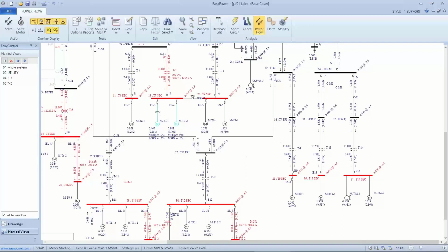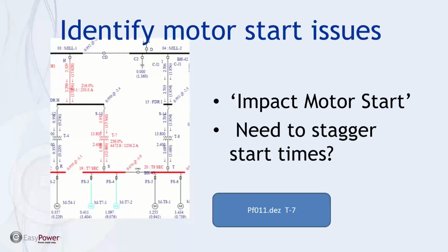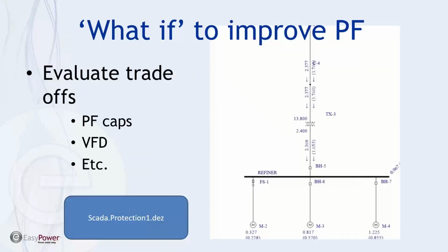And we may want to have a staggered start requirement or soft starts with different time settings if we're bringing up these motors. Now, let me just touch on power factor, and then we'll get back to a couple of the questions.